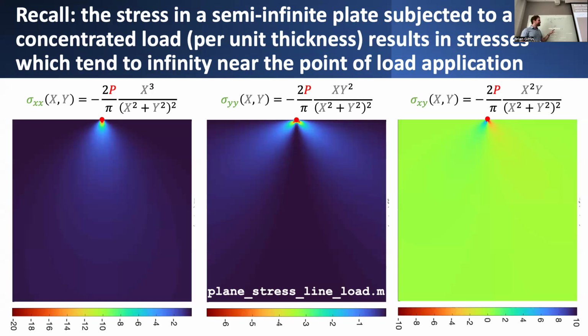And this assumption ultimately breaks down, obviously, if we have a situation where the stresses become infinite, because we know, and this really is a good segue into what we'll discuss in chapter 4, that a lot of conventional materials cannot sustain an infinite stress. At a certain point, they'll reach some kind of critical failure stress. Beyond that point, either the material will fracture and fail, and it won't be able to sustain any stresses after that, or maybe it'll start to yield and permanently deform. But it'll certainly never be able to achieve an infinite state of stress.